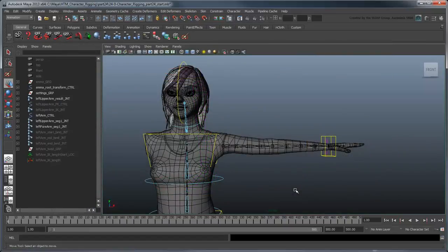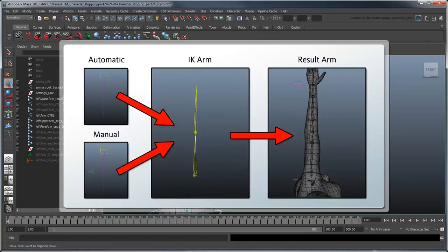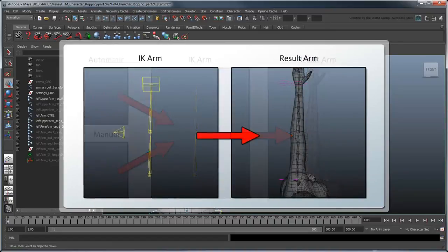However, because of the wide range of movement for the arm, an animator will usually want direct control over the elbow's twist. Therefore, a no-flip solution wouldn't be very useful, so we aren't going to bother worrying about it. This simplifies our rig requirements considerably, because we only need to deal with this one IK arm instead of implementing a dual IK arm system.